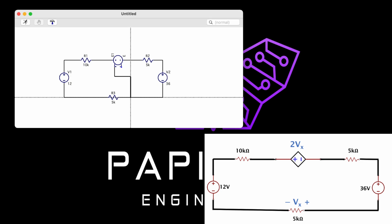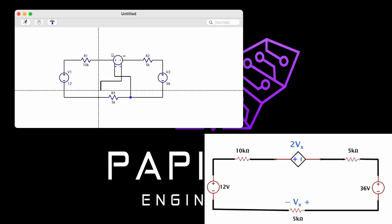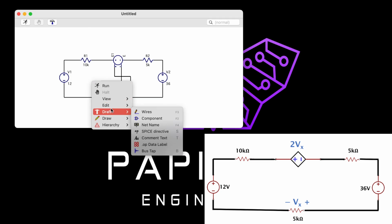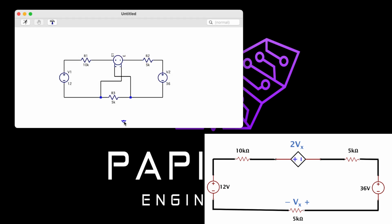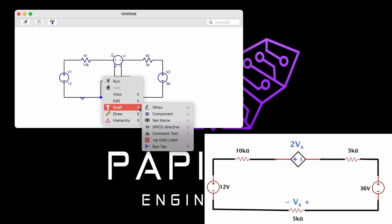But what's important is that you have the polarities correct. So if you have the positive end of your voltage dependent source, it is connected to the positive terminal, which is on the right side of the 5 kilo ohms, and the negative of my dependent source has to go to the left of the Vx, aka the 5 kilo ohm resistor. So from there you go to the net name, include a ground to this. The ground can go certainly anywhere, but it makes more sense in this case to put it towards the left where I just placed it.